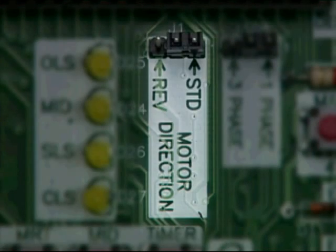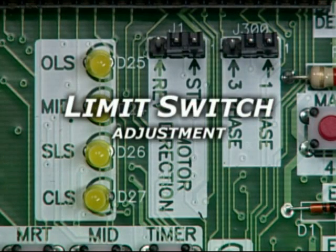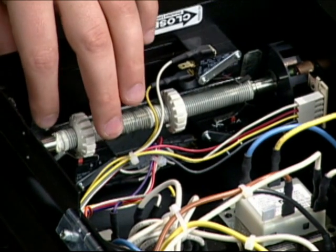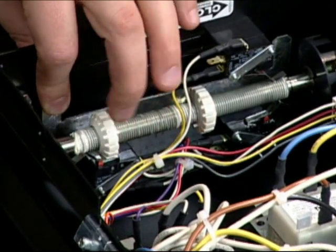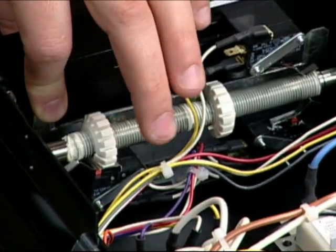Before we review the steps on how to change the motor direction on your operator, first we need to review how to make limit switch adjustments. Make sure that the limit nuts are positioned between the limit switches before proceeding with adjustments. Depress the retaining plate to allow the limit nuts to spin freely. To increase door travel, spin the limit nut away from the limit switch. To decrease door travel, spin the limit nut towards the limit switch.